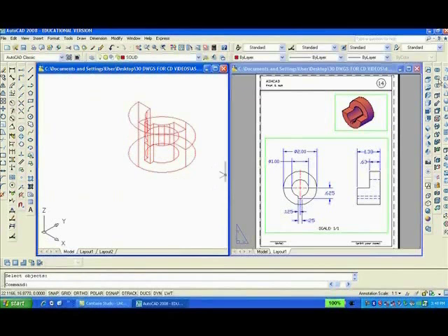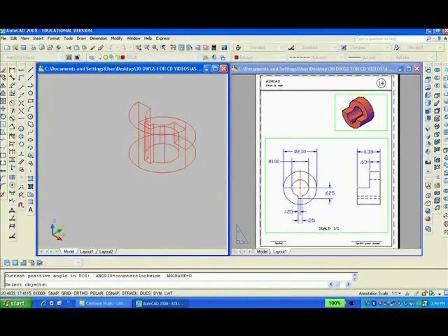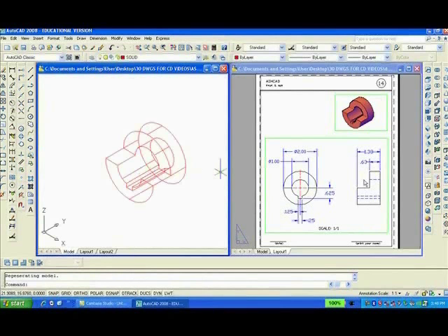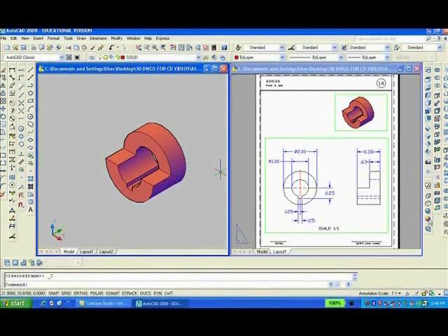Also, I think I forgot to subtract them, so we're going to have to subtract from here. Enter, that, enter. And then we're going to have to use the 3D rotate command. Select the object here, and we're going to put that at the center line here. Click on the red axis and type 90. Hopefully it's right. I'll add shading.